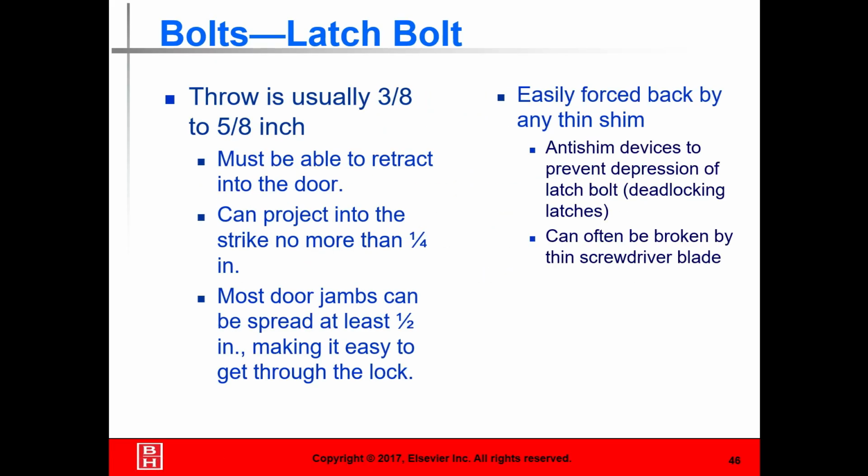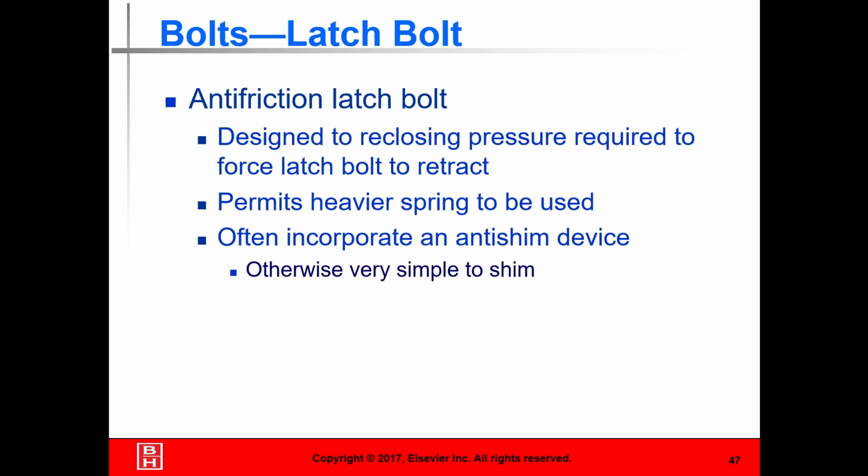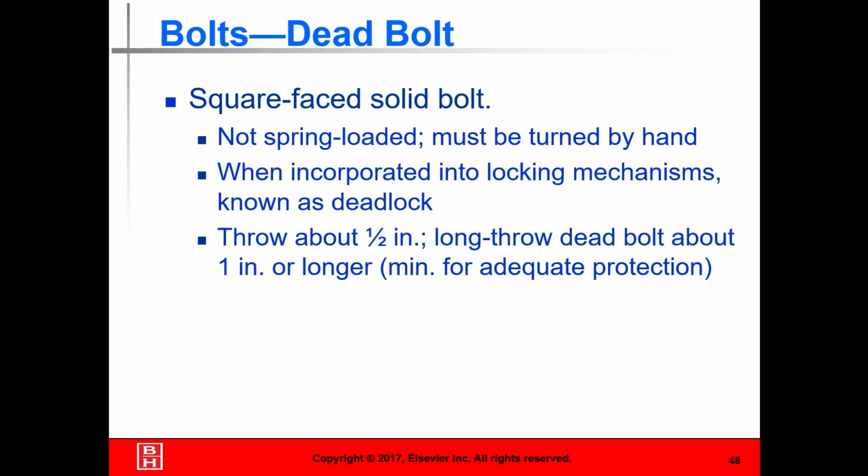The throw is usually 3/8 to 5/8 of an inch, depending on the door jamb and how everything comes together. Anti-friction latch bolt, designed to reclose. Reclosing pressure requires force with the latch bolt retracted, permitting a heavy spring to be used, often incorporated with anti-shim devices.